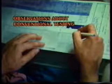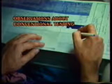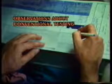Investigators have looked further at the interpretation of traditional gas well tests and have learned, first, that more information about the well may be obtained if the testing procedures are modified somewhat, and second, that as a means of estimating performance, the AOF plot may be misleading.